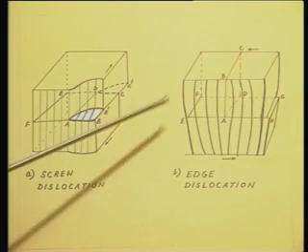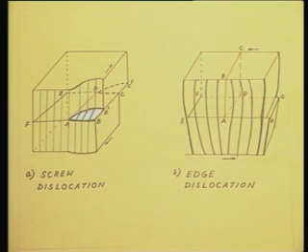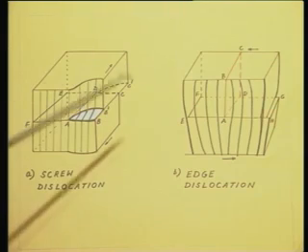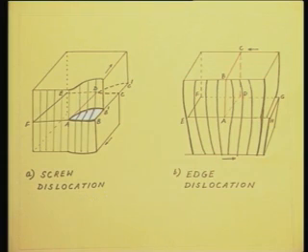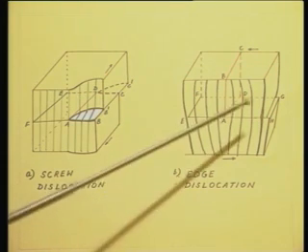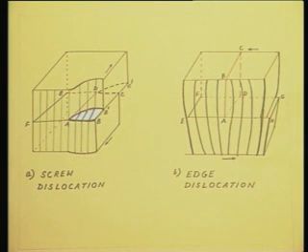See, if you view it in 2 dimensions, then all these black and red lines actually signify the array of atoms. Atoms are placed along this array. So, what you have done is you have created an extra half plane, it is not continued throughout the crystal. Only in the top half you have created an extra half plane of atoms. This is called an edge dislocation, extra edge. This is because the top half of the crystal has got displaced by half an atomic spacing.